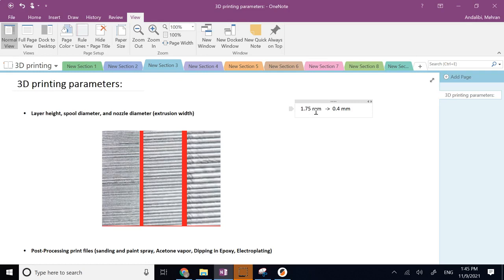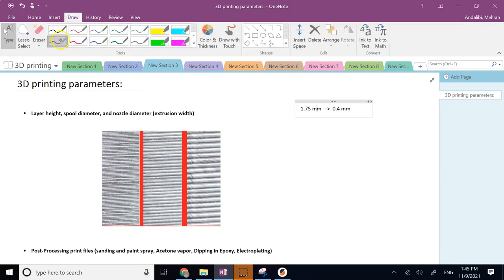Now, one other thing we have to pay attention to is that when the material is being printed, the thickness of the molten plastic is not going to be the same in all directions. Although we say the diameter of it is 0.4, the plastic coming out of the nozzle is not really a perfectly cylindrical shape. What you have is a slightly squeezed cylinder like this. So you will see this kind of plastic coming out of the nozzle.